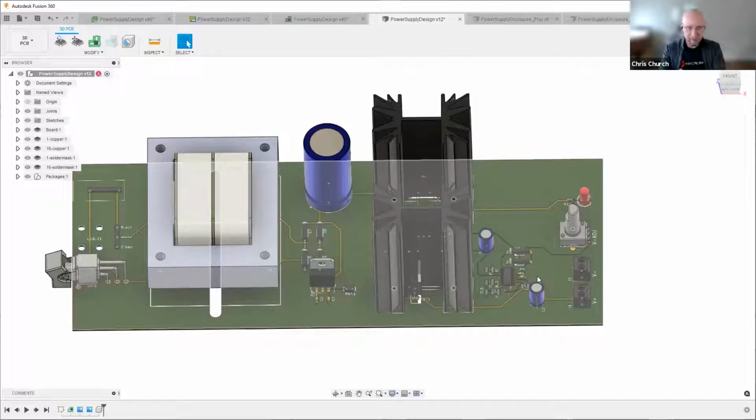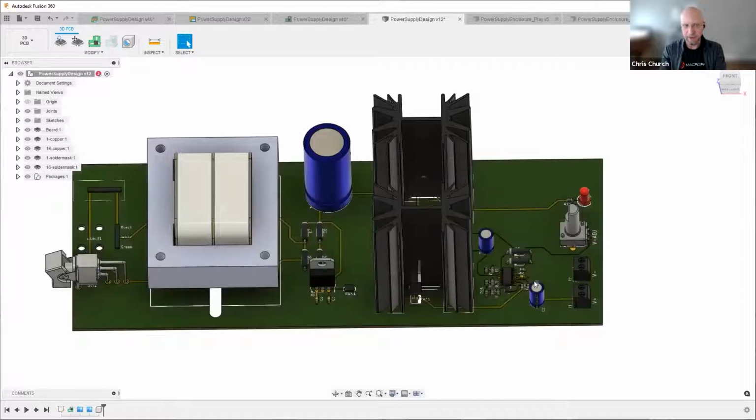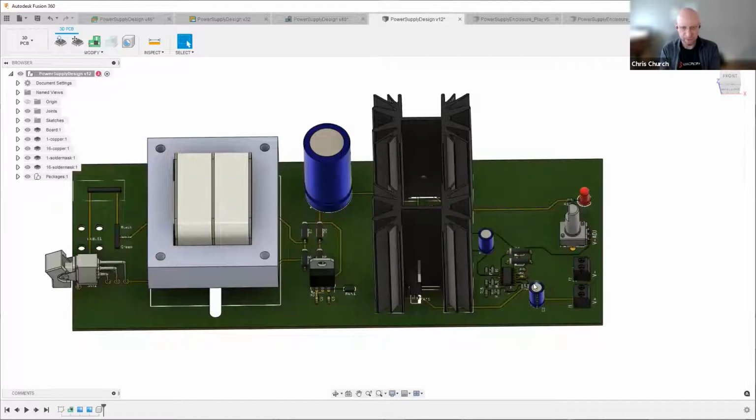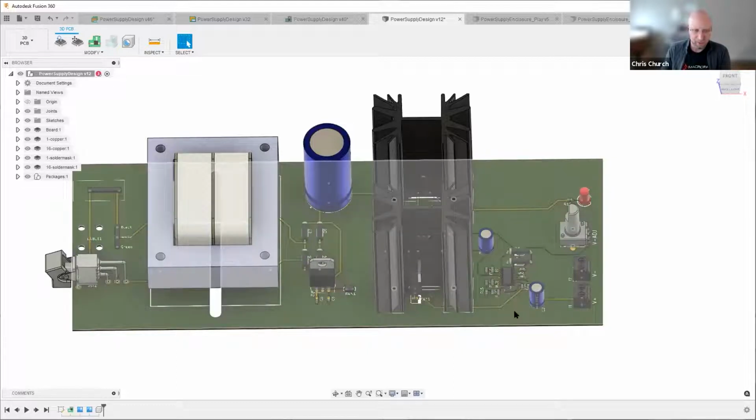But let's think about this one. As you said earlier, this is primarily an analog device. You want to test it by feeding power in and reading the voltage off the outside on the right side there and adjust that potentiometer. So the first thing, how we would typically approach that is we would create what's called a test fixture. Because we are dealing with AC on the left side of that circuit board, it could be very, very dangerous. And we want to protect that operator from it. So we're going to be creating an enclosed fixture. And plugging in wires and screwing them adds a lot of money and cost. You don't really want to pay someone to screw those in.